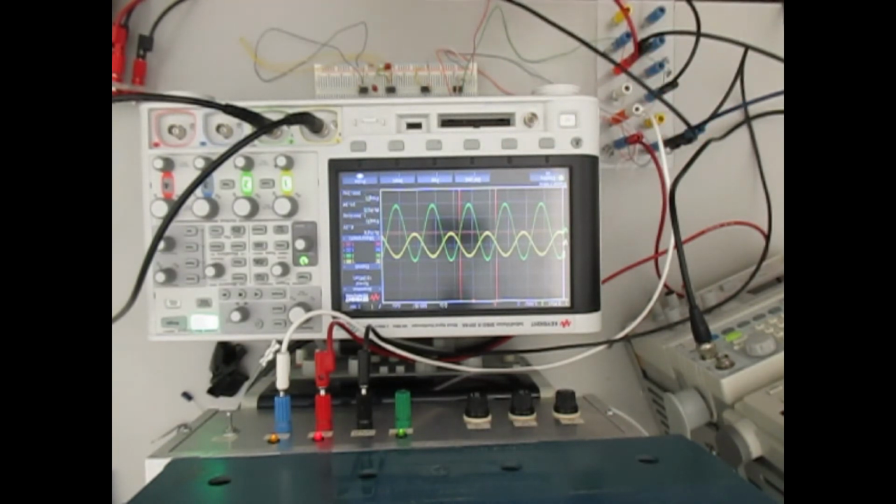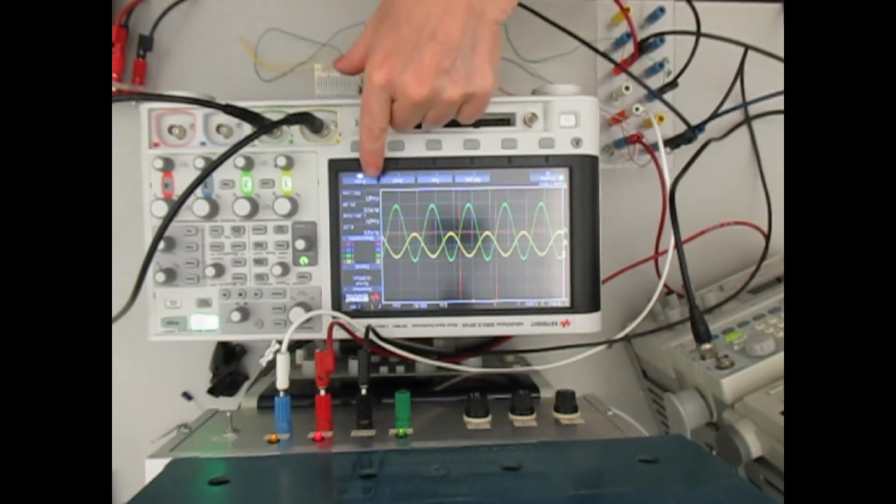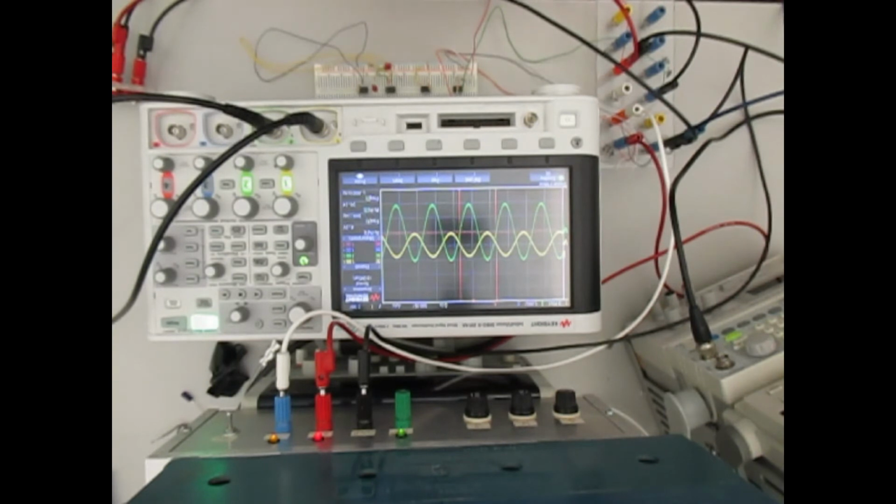Because we had RF is 3.3 and RI is 1K. So that gives us a gain of 3.3, and it should be inverted. And 6.2 is the input, and 20 volts even is the output. Okay, so 6.2 times 3.3, that's 18, it's 19. So it's pretty close.